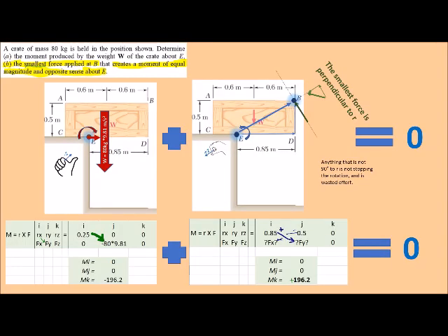Rather than going through the pain of analytic and numerical solutions in Excel and Mathematica, the other way to solve this is graphically. And by graphically, I mean you're going to look at the picture of this and think through intuitively what the answer should be. Remember, part of this force is going to be creating rotational motion, and part of this force is going to be creating translational motion. If we want the entire force to go into nothing but stopping rotation, we want the entire force to be perpendicular to this position vector.